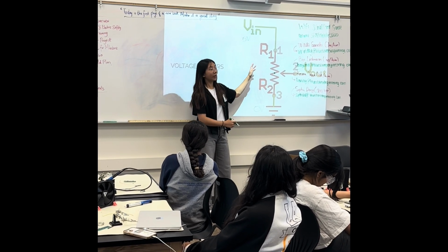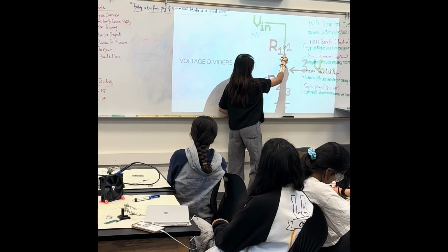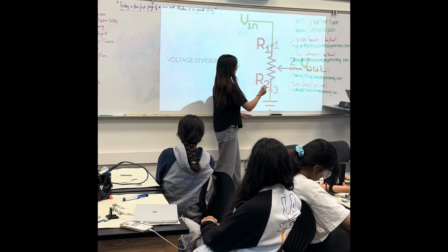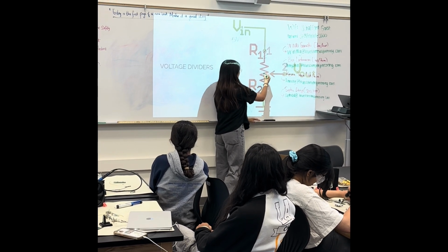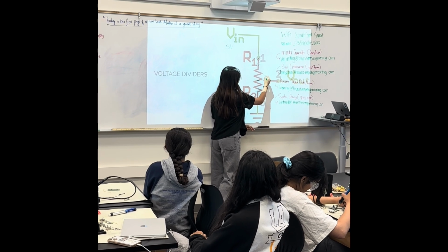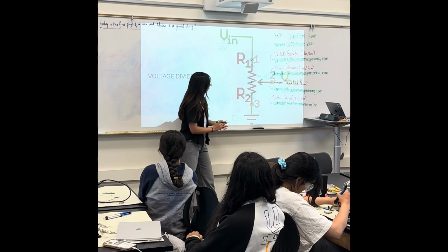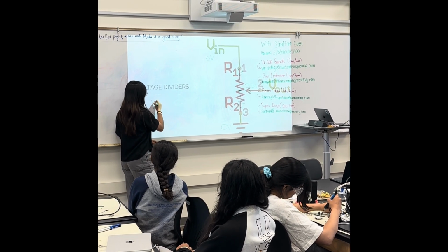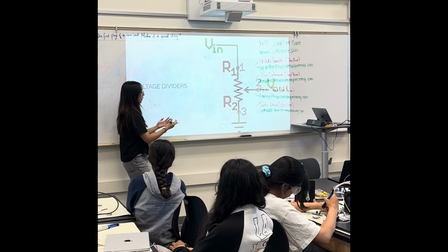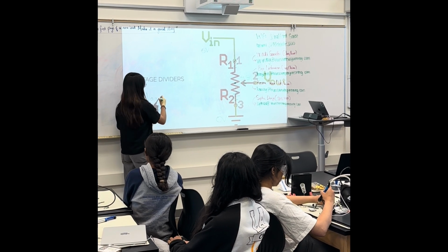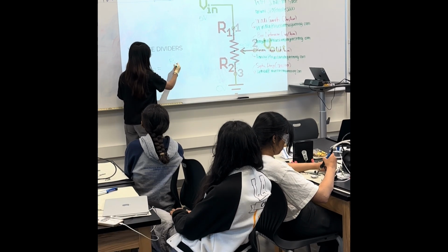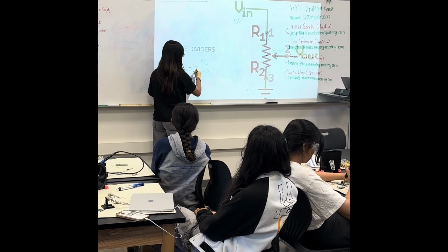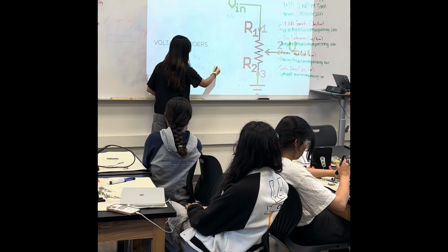Also, sorry, this picture is a little bit confusing. Resistor 1 is its own resistor, and resistor 2 is its own resistor. So you need two resistors. And then you want to take a point in between them, which goes to the Raspberry Pi, and in our case, we want this to be 3.3 volts. So essentially, we have this equation where V out, the result of using this voltage divider, is equal to the ratio between the two resistors, and that ratio multiplies V in.